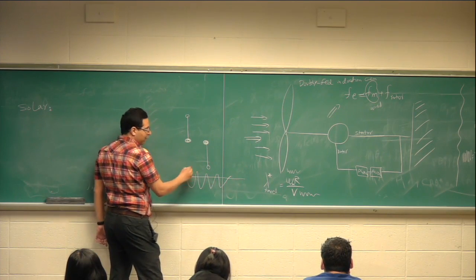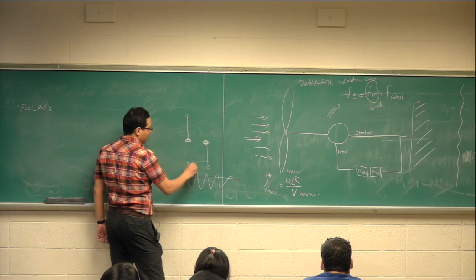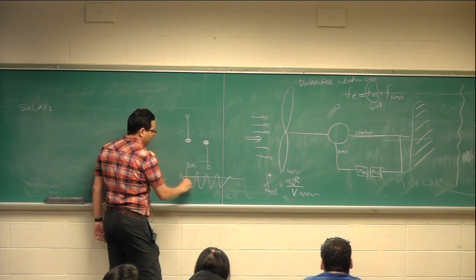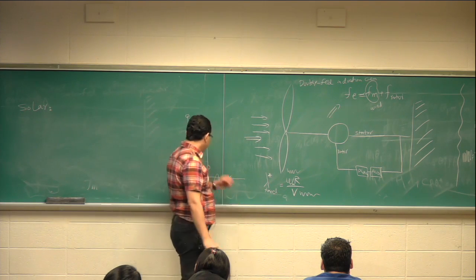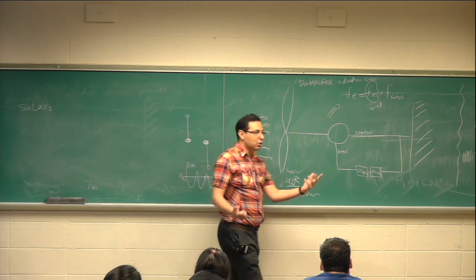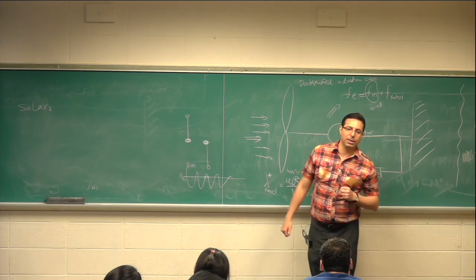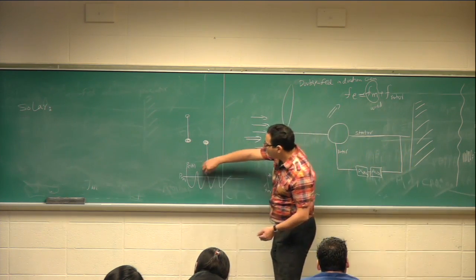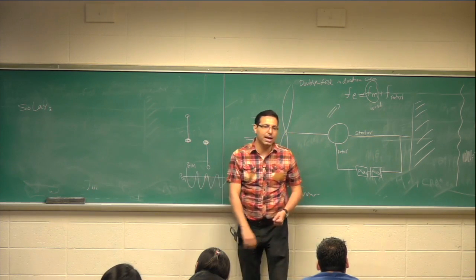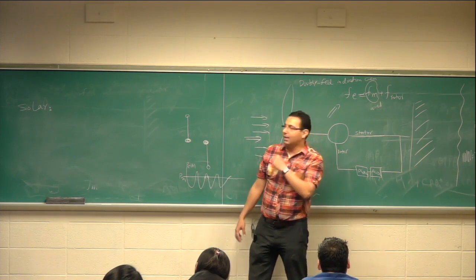The sinusoidal signal is P electrical, this is P mechanical. You're going to get at least two equilibria. One is stable, one is not. Since there are two equilibria, we're not going to get global stability. So the best thing that we can do is to maximize the region of attraction around that good equilibrium. And still there is no guarantee.